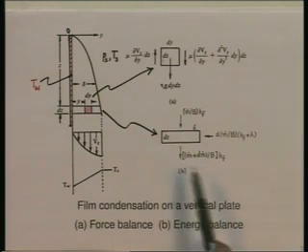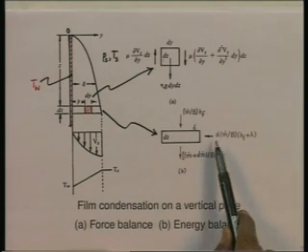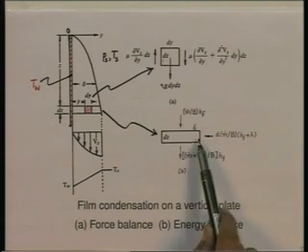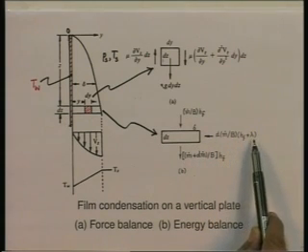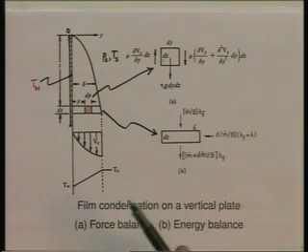In the flow going out, again it is saturated liquid. So, again I multiply the mass flow rate by H f, and in the flow coming in, that is, the condensation taking place here, I multiply by H f plus lambda, because it is the enthalpy of saturated vapor which I have to take. The saturated vapor condenses at the liquid vapor interface and then enters this control volume.